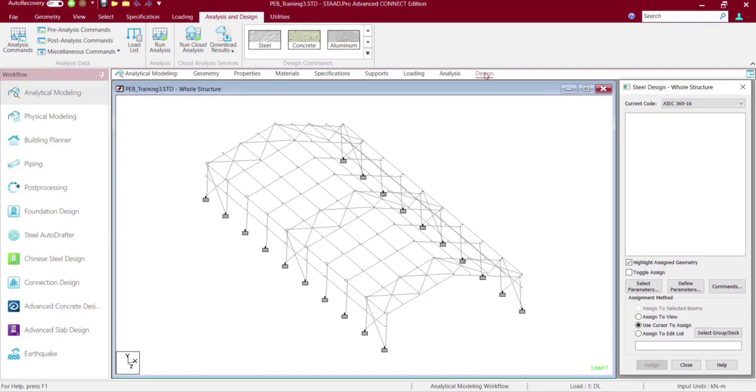Now, what are the parameters related to the deflection? Like DFF, that is the deflection limit, then the reference nodes to count the deformed shape to calculate the exact deflection. These reference nodes are denoted by the parameters called DJ1 and DJ2.